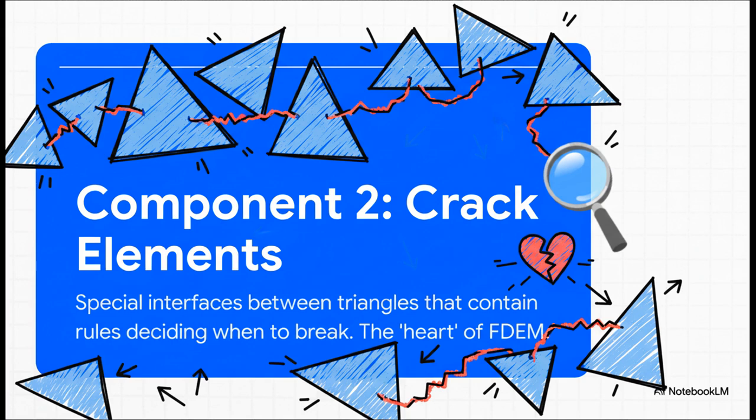In between every single one of those triangles, FDEM sticks these special little things called crack elements. Think of them like an intelligent glue holding the whole thing together. And this glue has a rulebook based on stuff like tensile strength and cohesion, and it's constantly checking the stress. When the stress gets too high, the glue decides, all right, it's time to break. This right here is the absolute heart of FDEM.